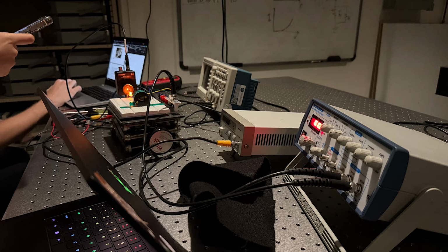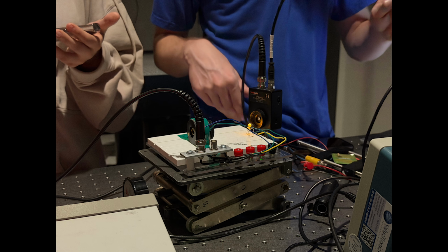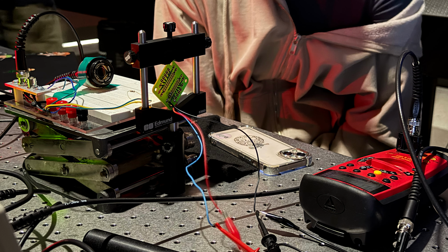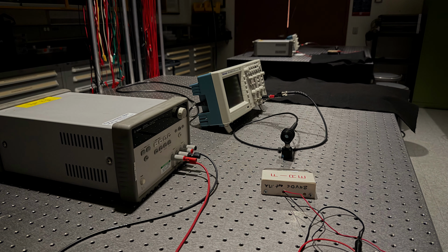We began by aligning the APD and reference pin diode with the LED, covering the setup and adjusting the LED amplitude until both signals were visible. Then, we switched to the second pin diode to record open circuit voltage and short circuit current versus optical power. After that, we replaced the pin diode with the photoconductor and measured how its output voltage changed as we adjusted the LED. Finally, we measured the pin diode's temporal response with and without the 47 ohm load resistor to see how the fall time changed.